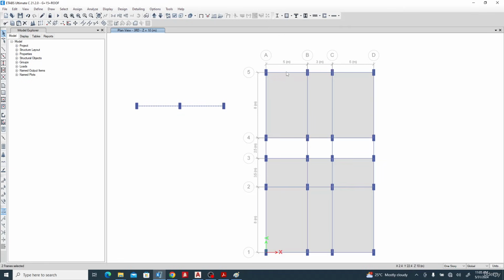So you can see the beam has been selected. You will notice that some beams we have here have not been broken down. So you can decide to break it, and you can also decide to leave it like this. The reason why I would advise you to break it is that when you move to RCDC for detailing or calculation sheets, it will split the beams like this. But if you decide to leave it like this, RCDC will just detail it as a whole 13-meter beam, which is what you don't want.